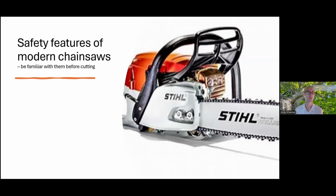Safety features that we should be familiar with on a modern chainsaw. That inertia activated chain brake. As I mentioned, it doesn't work quick enough. It doesn't work 100% of the time, but it is a nice feature to have. Spring-loaded system where if kickback occurs, it's going to stop that clutch and stop that chain from turning.